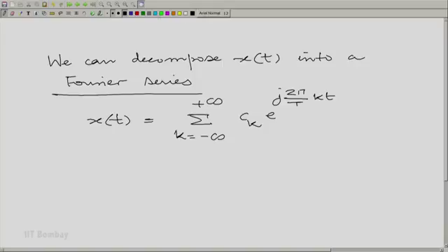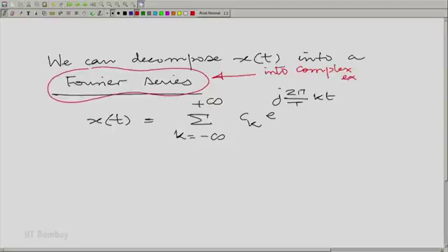I do not want to say too much about Fourier here, maybe we will take it up some other time, but Fourier is a very well known name in all contexts in signals and systems, in system theory, in control engineering, a very famous mathematician, a very famous name, with the whole concept of decomposition in terms of sinusoids named after him. This decomposition that we have been talking about, thinking of a periodic waveform as a linear combination of sinusoids or complex exponentials with frequencies equal to multiples of the fundamental, is called a Fourier series decomposition. That is what we have written here. So, this term Fourier series is a term that we shall use again and again, essentially a decomposition into complex exponentials or sinusoidal components. In this case, we are talking about complex exponential components.